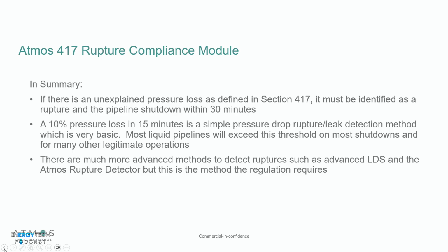This takes an average pressure and detects a pressure drop within 15 minutes. We record everything. We show when it's violating that, when it's not. That way, our clients, once they implement that, are fully compliant. However, it will alarm a lot. So what we say is, since you already have a more effective leak detection system that is tuned to normal operation, there's a caveat in this rule, and I'm sorry it's not on that slide, that states unless it's normal operation. I see. So our more sophisticated systems are tuned for all normal operations, so they don't alarm during them.